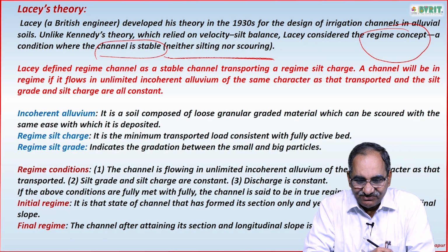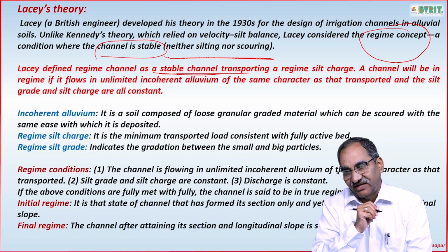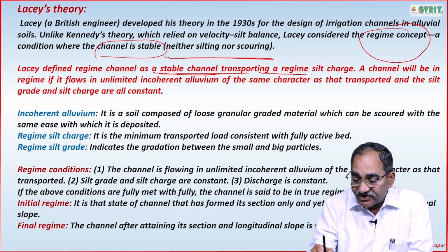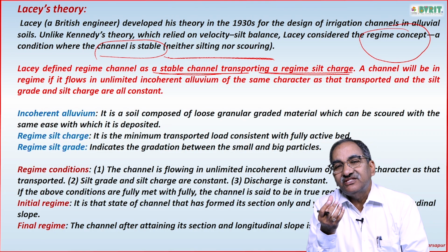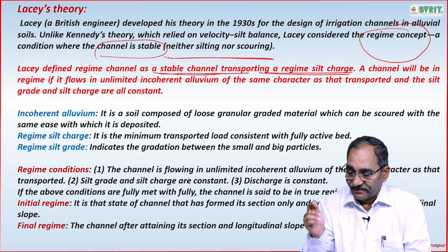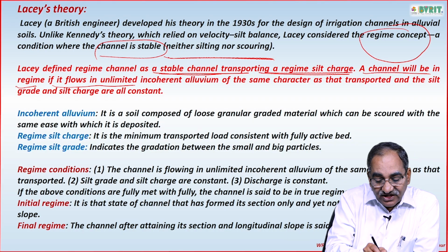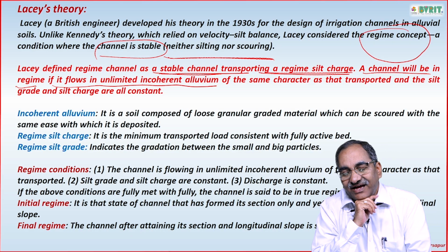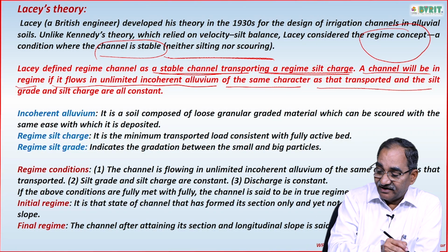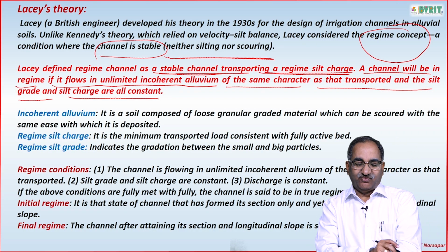So what is a regime channel? A regime channel is a stable channel. First, a regime channel means transporting a regime silt charge. Charge means quantity; please remember, silt charge means silt quantity. A channel will be in regime if it flows in unlimited incoherent alluvium of the same character as that transported, and the silt grade and silt charge are constant. I will explain these points.